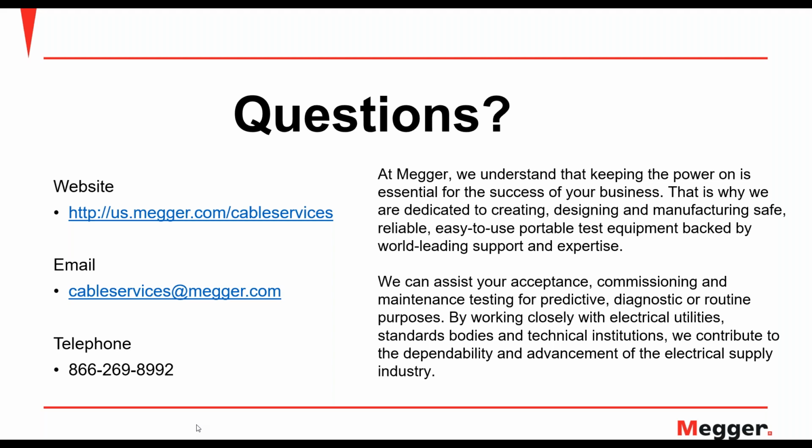So that's why there's really no one answer that fits all here, which is kind of why we showed the 3 tests and diagnostic tools, and how all 3 of them give you the complete picture, and you can use 2 of them to complement each other, because that's what they do. So if you run tan delta and get a good, passing measurement, you can know that the overall condition assessment of that insulation is good. Now, if you run a PD measurement and you find a localized weak spot, that could fail in the near future. And that's the beauty of running both tests, having the ability to identify, localize, and fix that issue, and then put that, like brand new cable, back in service.